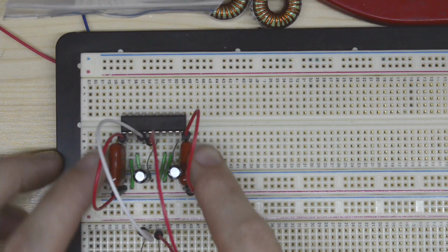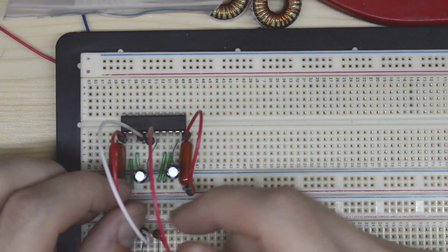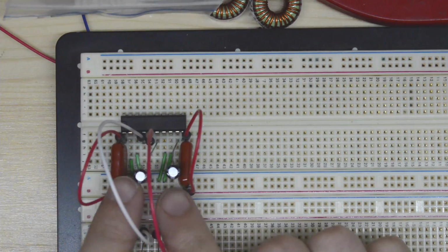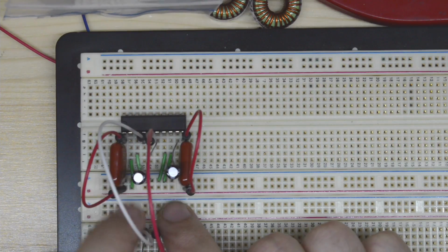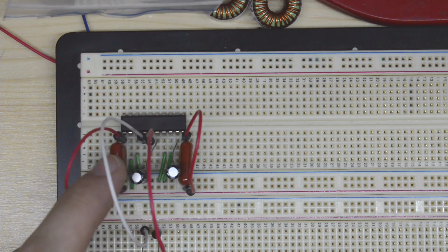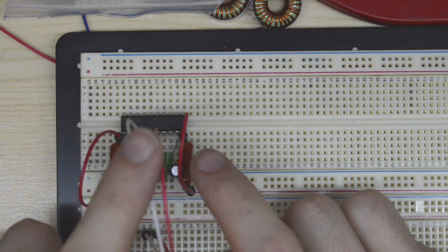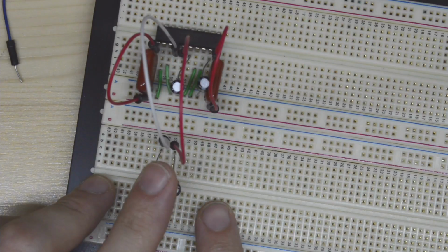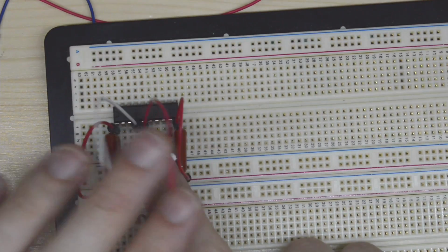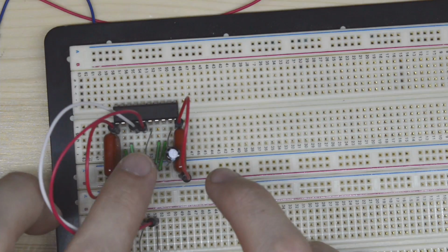We have each voltage in with capacitors that are set to ground and a jumper going to VCC. Then after that we have our shutdown signal set to high. Then we have our mute set to low. Next to those is the left and right, which are connected to two capacitors. Then after that, we have a capacitor here set to ground, two other pins set to ground, and another pin set to ground.